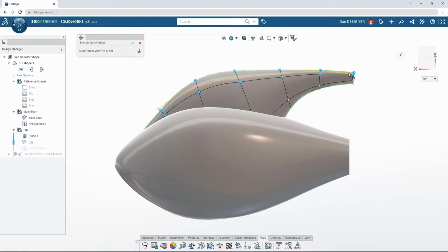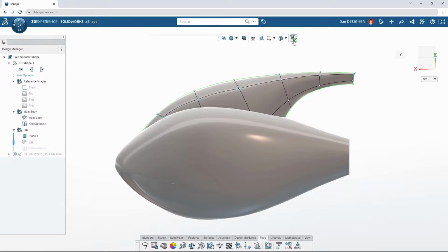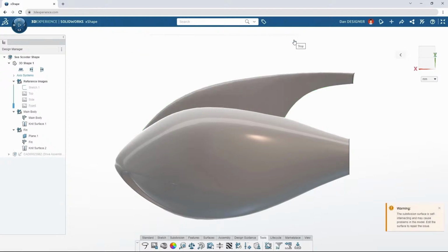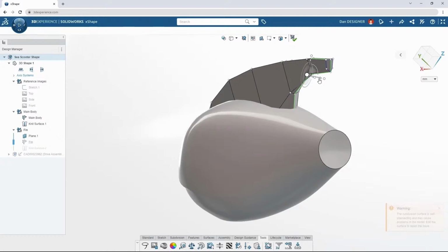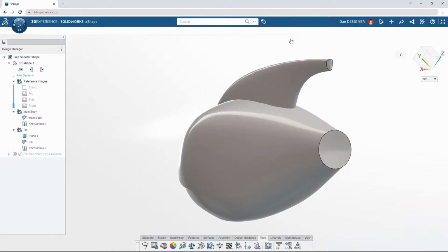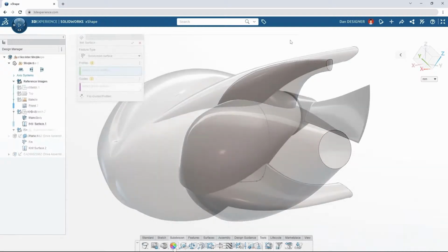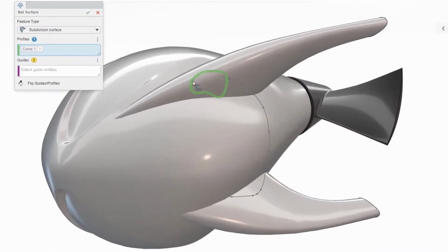And we'll just go ahead and draw a line where we want that to kind of tune our shape. And it gives a really artistic capability to modeling here. Now we got an error that some of the mesh was intersecting, and we can use the visualization tools to see exactly where that problem is, go in and tune that so it's nice clean geometry.